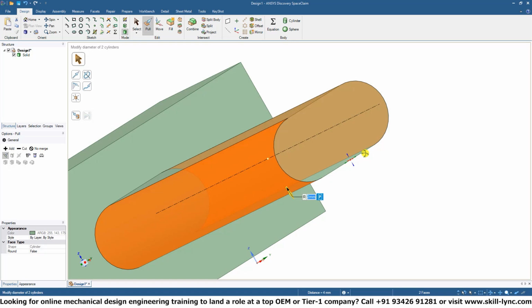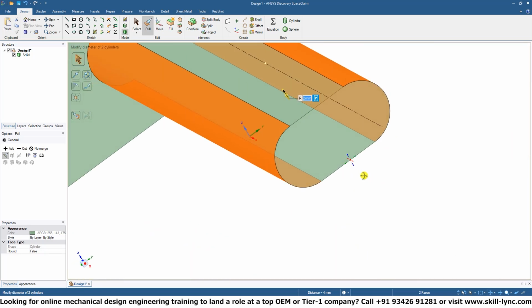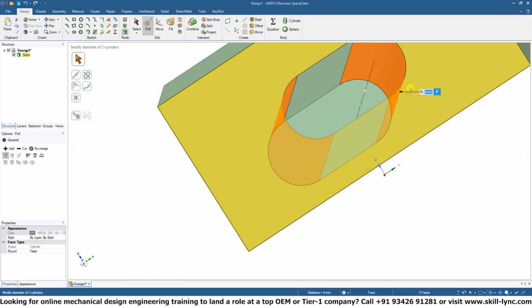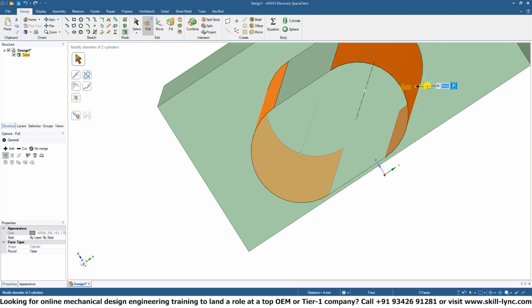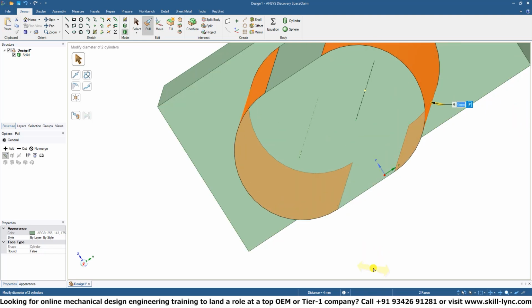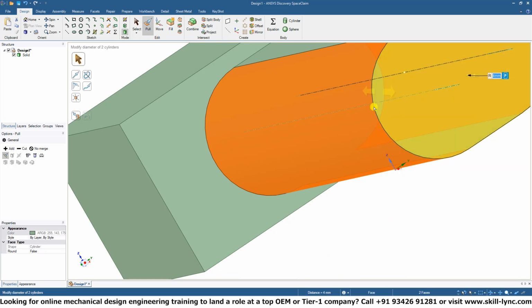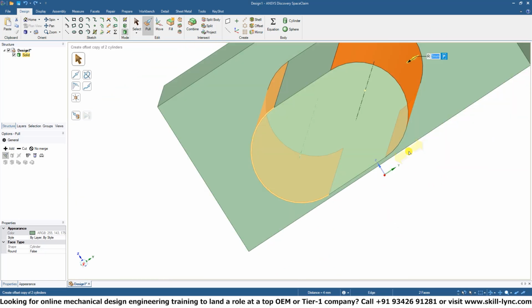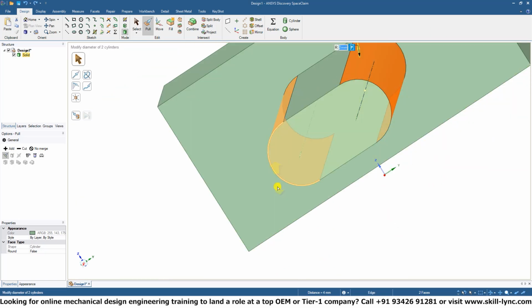There's one very important feature to note. You can see over here, the maximum that it lets me do is 2 millimeters. What if we actually define a value larger than 3 millimeters? It actually increases or edits the whole area. It actually adds material. As you can see, it increases our initial rectangular surface area that we had.